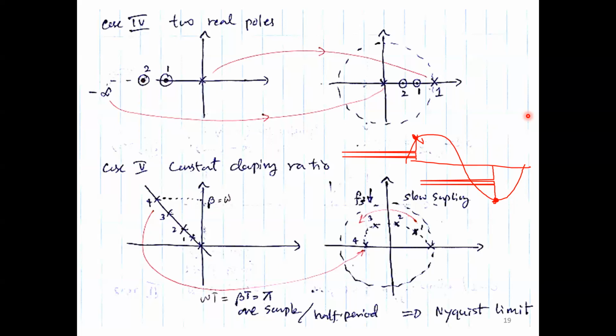So what we have learned there is that there are ways to find out whether you are doing sampling accurately or in a fair manner. If you want to take so many samples, that is not good because that is not the purpose. The whole purpose of going discretization is to reduce the bandwidth, reduce the data load. Having to deal with the continuous system is a torture, because a lot of data is difficult. So reducing the sampling frequency helps a lot. Reduce bandwidth and a lot of convenience there.